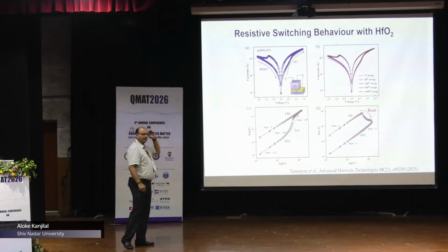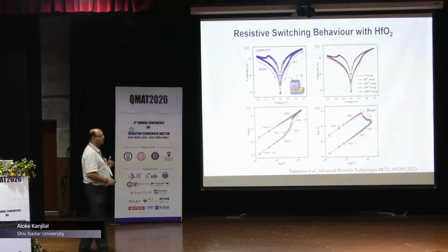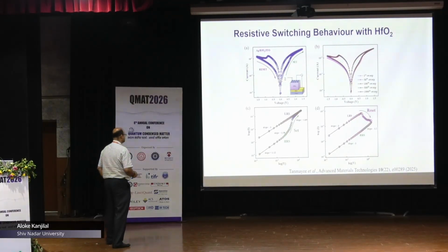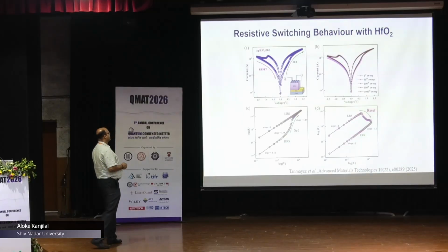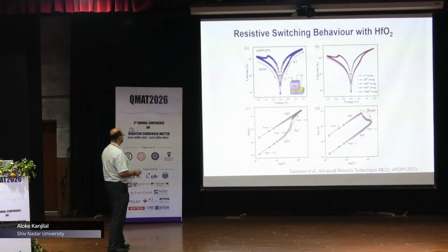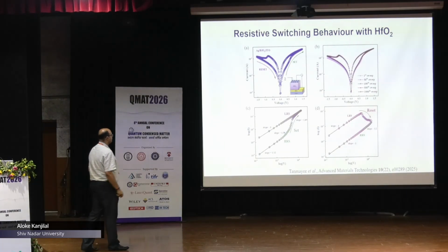In the beginning, before testing that one, we just want to see whether hafnium oxide is really working well, as the early literature people have been discussing. So we have taken the IV characteristics. You can see that it's a butterfly kind of structure coming, and this was set and reset, which confirms that the hafnium oxide layer performs very nicely, and it is very stable also.